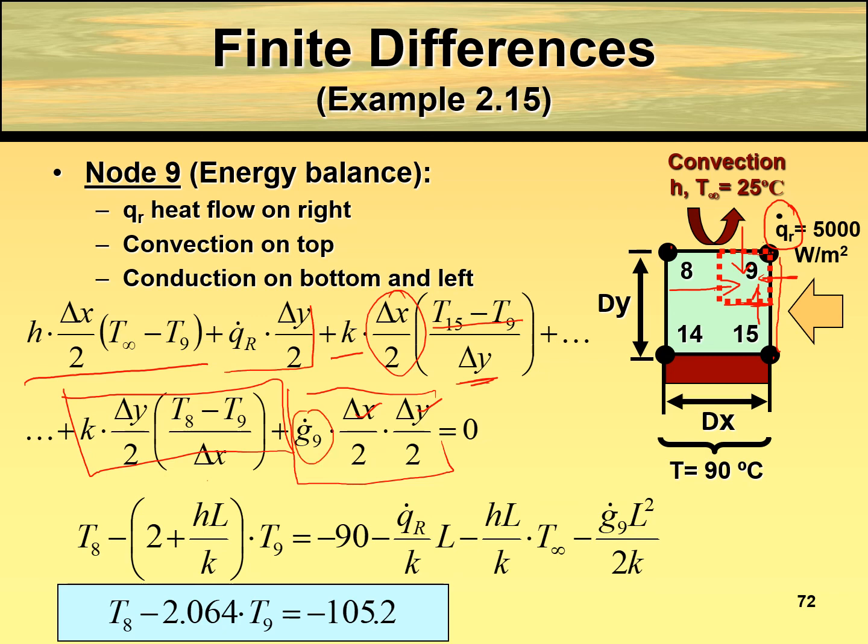Now this one here is your heat flux. So your heat flux is nothing but q dot, and the unit is watt per meter squared. Now if you want to change watt per meter squared to watt, you must multiply with meter squared, so that you can cancel this to get watt. So we have no choice but to multiply this with the area. So to multiply this with the area, this is actually delta y over 2. So this is the length.